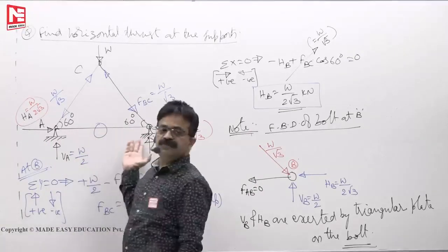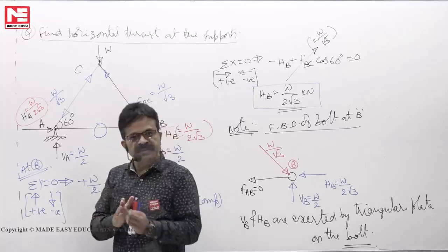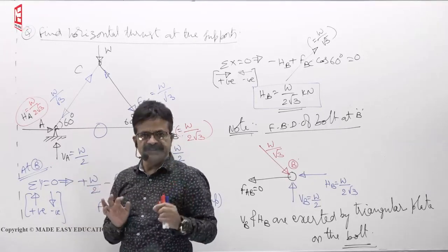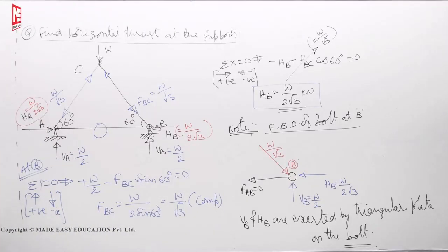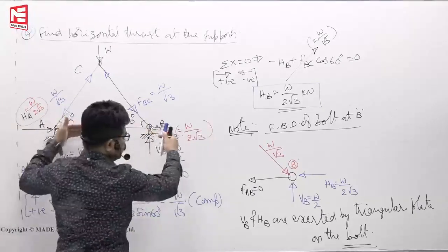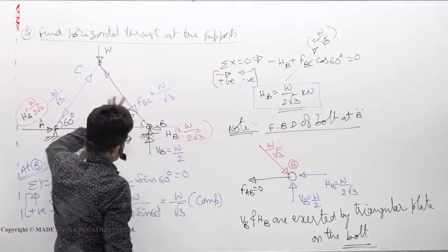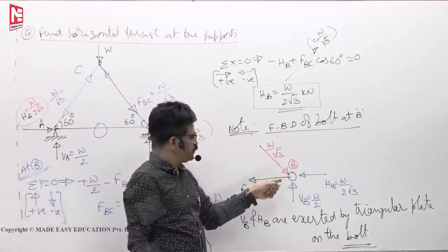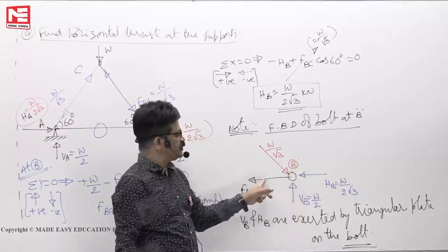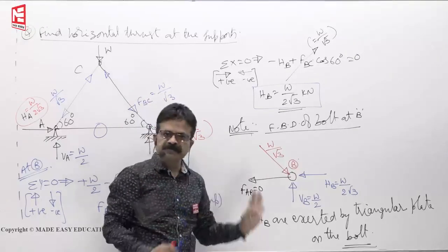questions. Why the force in the member AB should be 0, why it cannot elongate or contract, how connection is made, you should have a clear picture. Okay. So now I think from this free body diagram you will know that AB is not subjected to any compression. B and A are in equilibrium by themselves. Without this FAB force, these three are in equilibrium by themselves. This simply keeps quiet. AB member keeps quiet.